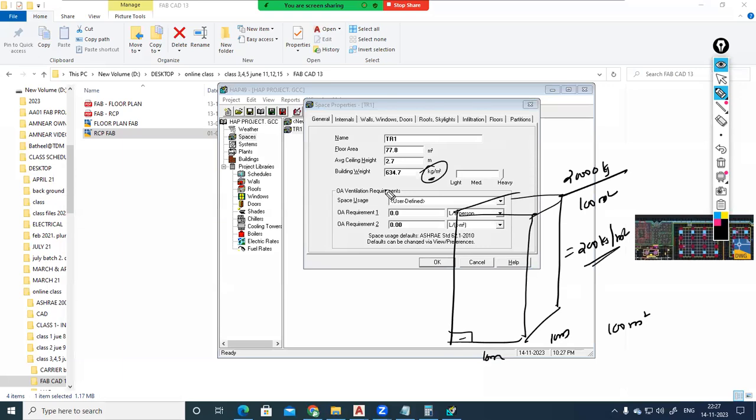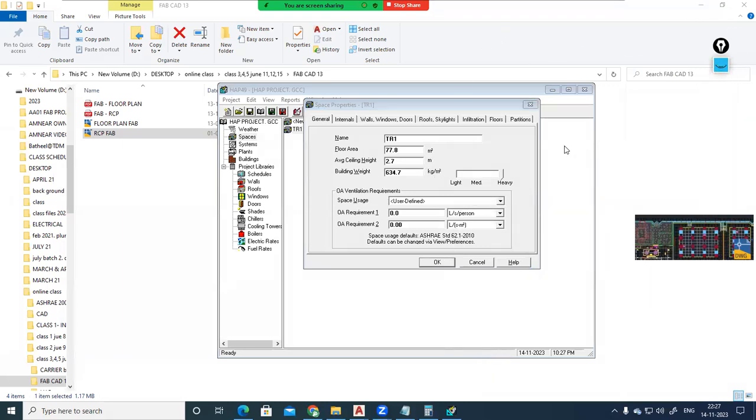That's why if the structural building weight is increasing, accordingly, the heat holding capacity of the building material will be increasing. Anyhow, 341 or 340, you can consider the average. You don't want to change it. If you don't know the light details or the heavy details or the medium details, you can consider that as building 341.8 kilogram per meter square.